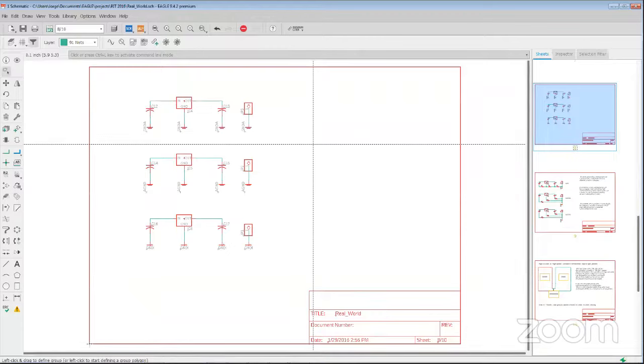If you just think of something as ground, you're kind of thinking of ground as like a big plane, an infinite pool where all the current goes into. That's not 100% true. Well, actually, it's not true at all. But for simple circuits that aren't at high speed, it kind of works. And that's why a lot of people get confused when they start working into more precise or high-speed signals, that you can't treat ground as ground anymore. You can't treat it as an infinite sink of current, because it's not.